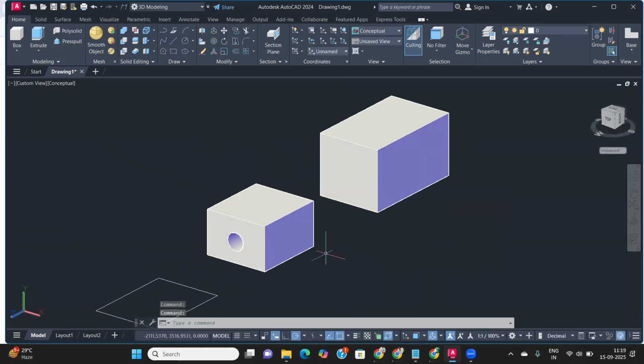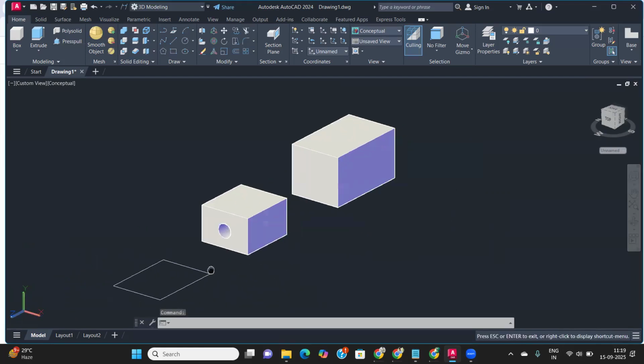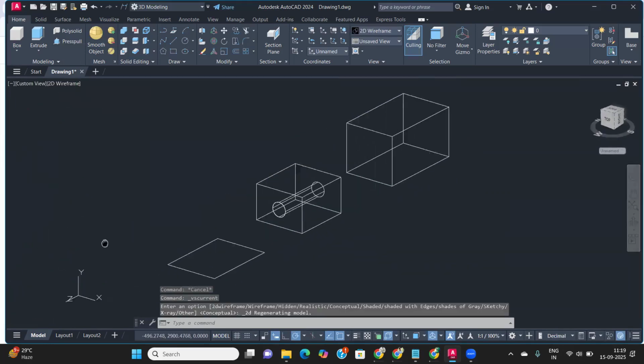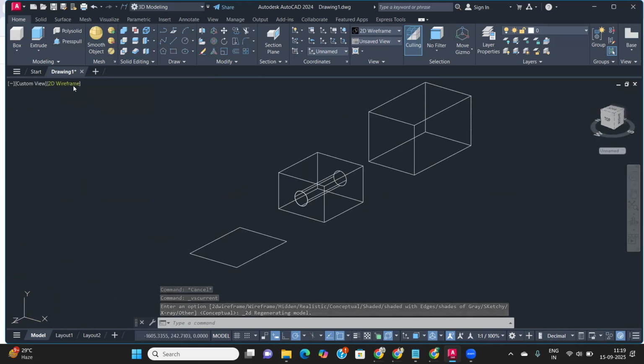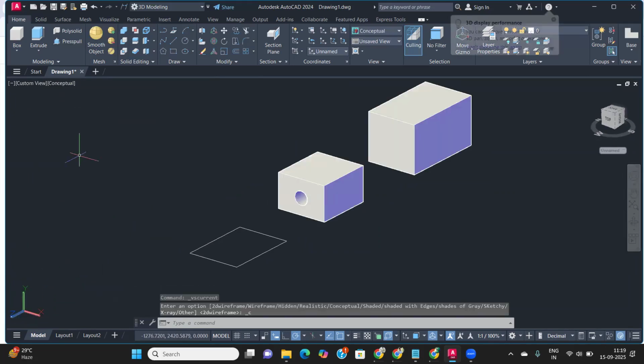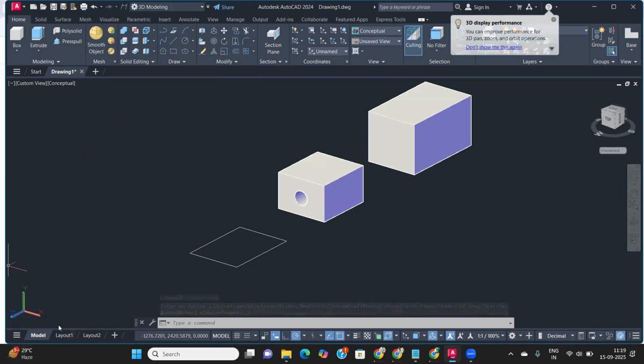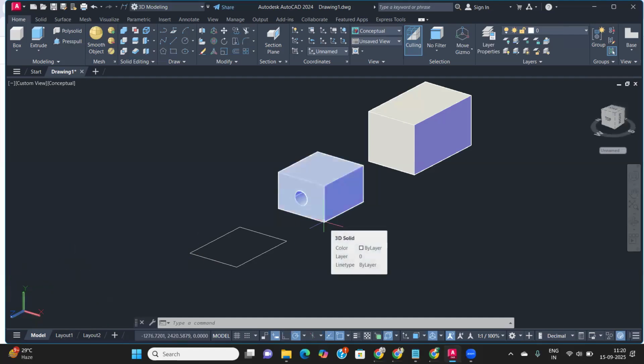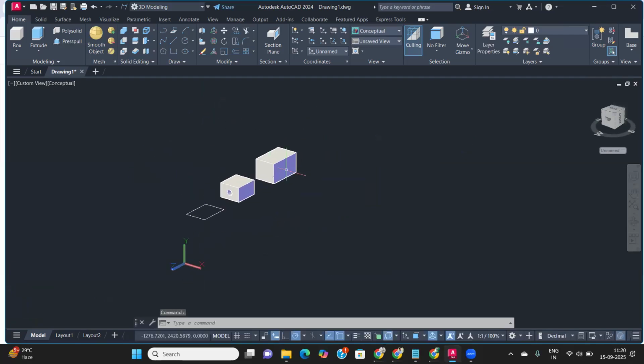Right, that's clear. And then here, we also remember the green color shows the Y axis, blue color shows the Z axis, and red color shows the X axis. Okay, and this is also useful. If you want to show the 2D wireframe here, we don't have to show the color format of these XY coordinates. But if you come to the 3D format, then what will be different? This will show the color format. This UCS icon shows the user coordinate system, which is really showing the 3D. Correct. Okay, basically how to switch the workspace and how to use the workspace.